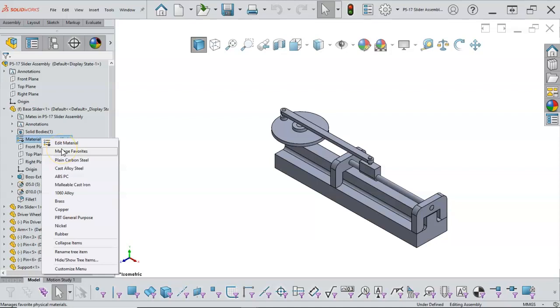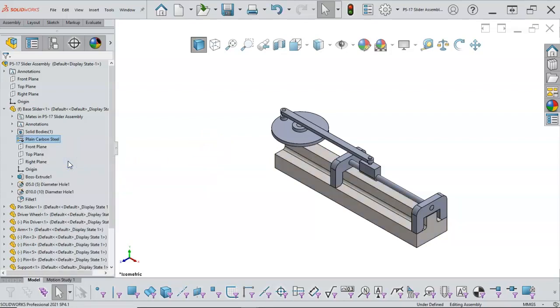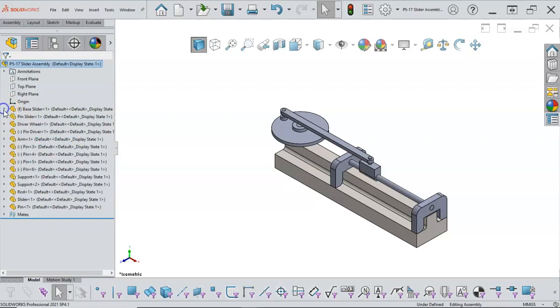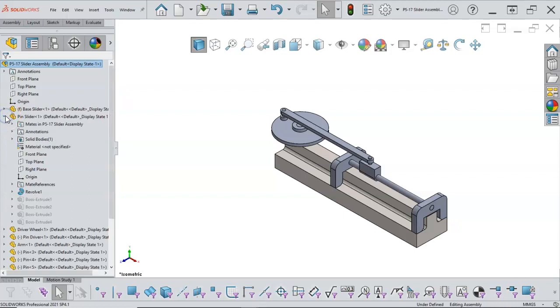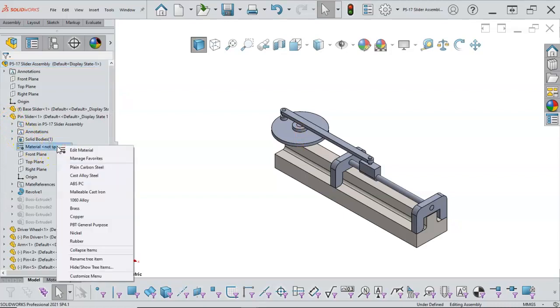And one of the other things with the tolerances is what material we're using. If I'm doing a steel pin to an aluminum disc, I would probably want a bearing in there because any RPM is going to gall up, and it really doesn't matter how much lubrication I put on that joint. It's just not going to hold up. So bushings, bearings, steel, aluminum, we're going to have to make all of those choices. So if I go with plain carbon steel, that's going to take more to machine, but it's going to be heavier. But I'm going to have to account for that in the tolerances.